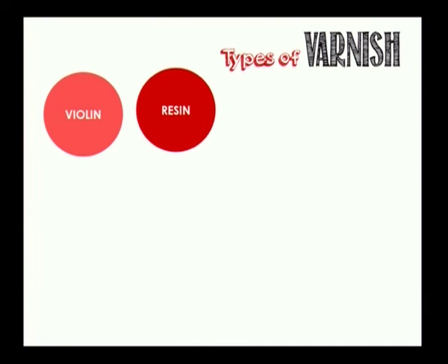Most resin or gum varnishes consist of a natural plant or insect derived substance dissolved in a solvent, called spirit varnish or solvent varnish. The solvent may be alcohol, turpentine or petroleum based. Shellac is a very widely used single component resin varnish that is alcohol soluble. It is not used for outdoor surfaces and where it will come into repeated contact with water, such as around a sink or bathtub.